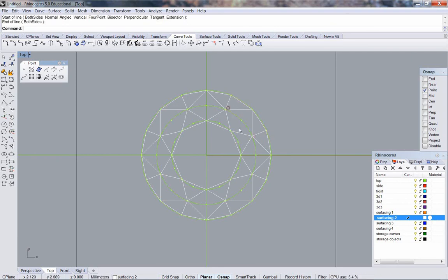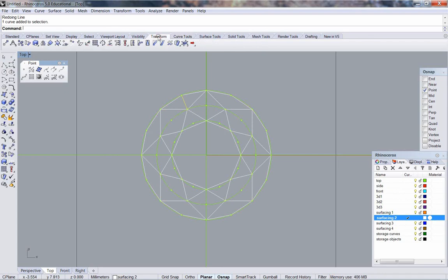Now there is an alternative to doing that. Instead of drawing each one, I can just draw the first one here and do the transform. Use the button that looks like a color wheel, polar array, center of array 0, or the center of the grid, number of items 8, enter, accept 360, and enter one more time to accept. And that will place them all the way around.